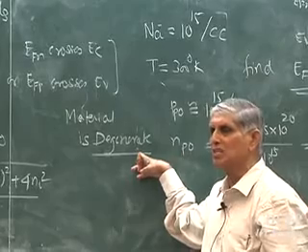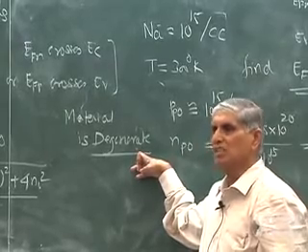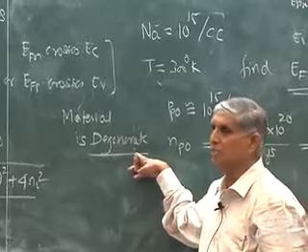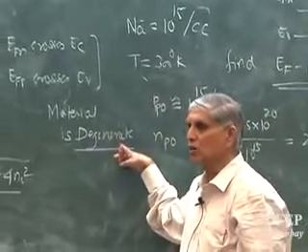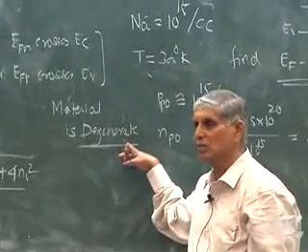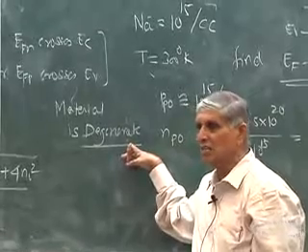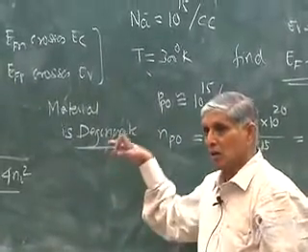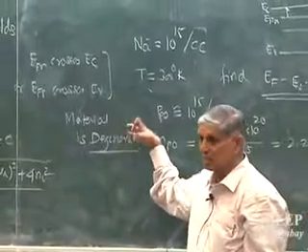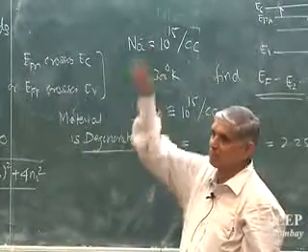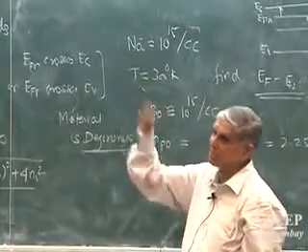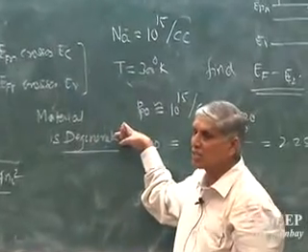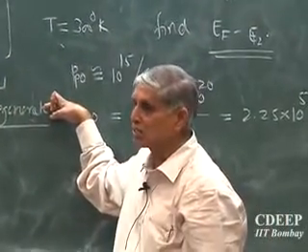Doping normally does not exceed the point where degeneracy occurs, at least in the part where transport occurs. The concentration of electrons and holes never exceeds so much that EF reaches NC or NV or something. But in reality, they may, because there are states and I can push further. Every state, I can push more electrons. But this essentially will not reduce the transport.